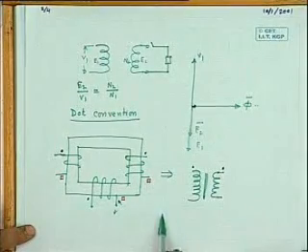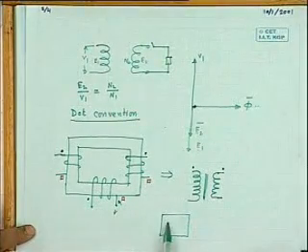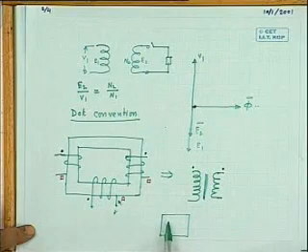For example, suppose you are given a transformer. In transformers, what happens is this: two terminals from the primary winding come out and reach you from the top box as two terminals, and two terminals come out from the secondary of the transformer, and you don't have any way to look at the sense of the winding. Suppose you could open it all together and see the winding moving like this, then no test is required. You can tell this is dot. But that is not possible in a practical transformer.